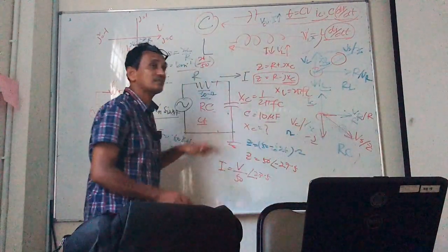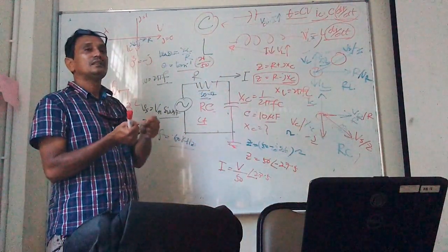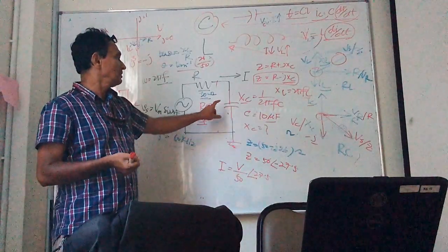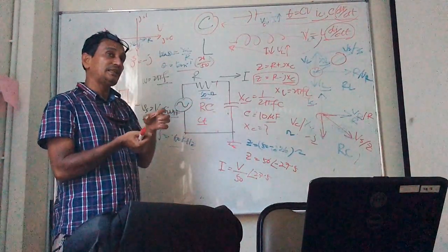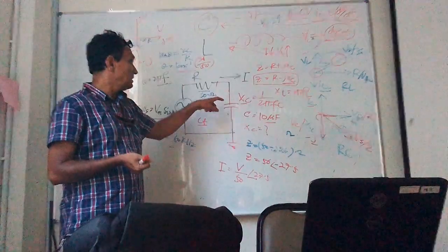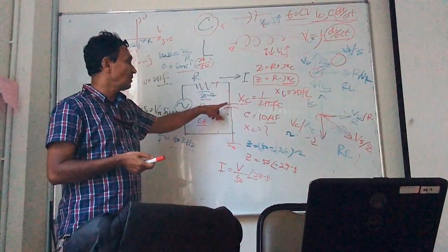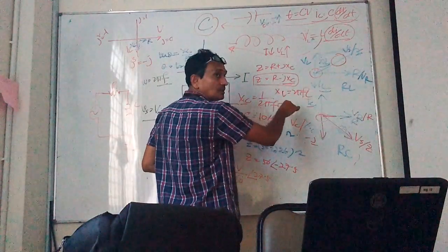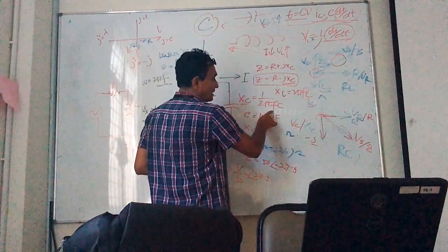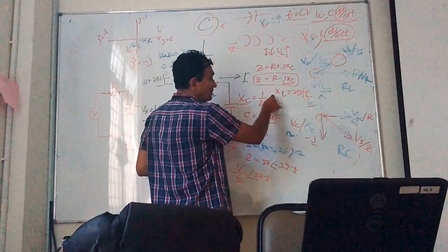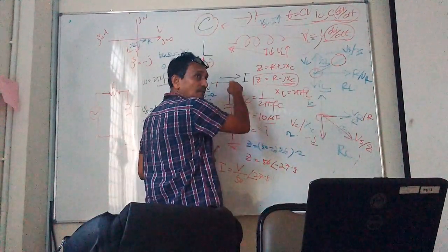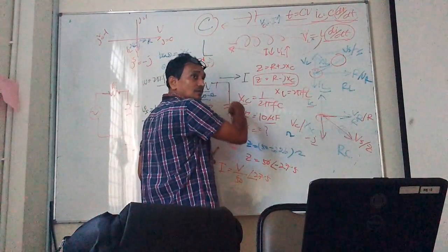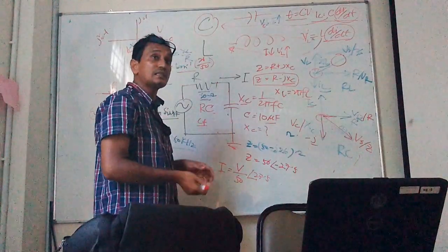Then how about the capacitor? A capacitor is actually an electric field circuit. So for the electrostatic field, always think that initially, at time 0, it offers no reaction. Time 0 means frequency is also 0, so it does not offer any reaction and allows maximum current flow initially.